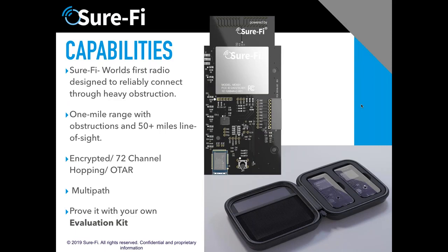Mario asked about WLAN transmission, point to point. I hope I answered your question, Mario. This is not Wi-Fi, and it's definitely point to point. It's 900 megahertz and, more importantly, chirp spread spectrum technology, which is what makes it so reliable. Bandwidth capacity, we probably need to talk a little bit about that, Mario, specifically because it depends on the application, with the different chirp modulations and things like that.